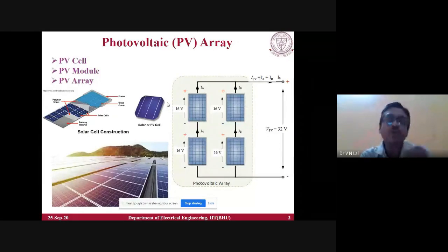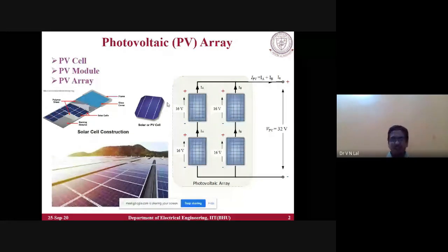I'm not going into deep detail, but a small difference I would like to mention is that the N-type layer in a solar cell's PN junction is very, very thin, so that solar photons can penetrate the N layer and reach the junction, release electron-hole pairs, and current will flow. This is the fundamental concept of solar current and voltage in a PV cell. We have to remember that a thin N-type layer is there.